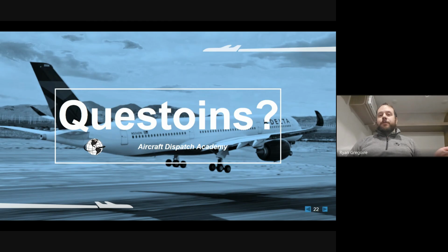So now you need to address that with the duty manager and maintenance control, saying, hey, we have this MEL that expires at midnight Zulu, but my flight's not going to land until 2 minutes after midnight, and I have no way to speed it up further. So what's your plan to do with this airplane? Because right now it's not legal to dispatch. Got it.